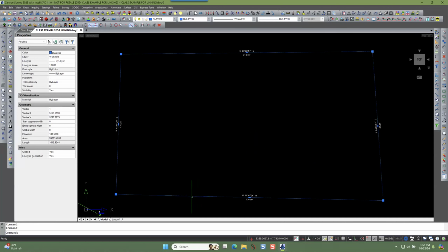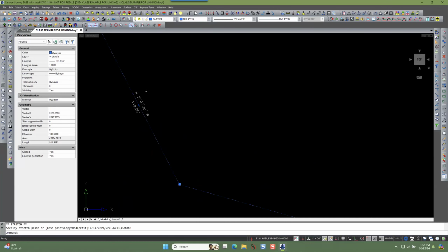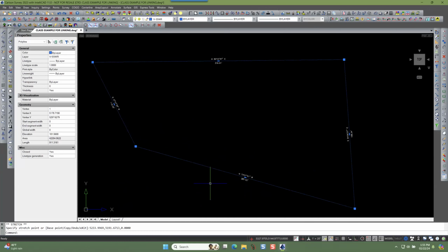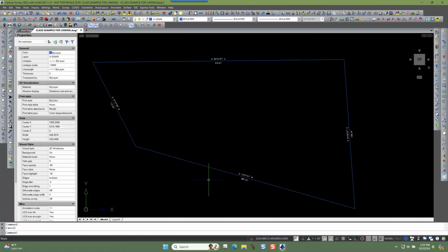Now, this was the other linking, linking labels with line work. So if I select that and say move this up, notice, keep an eye on those values. I had 176, and it was a north 02. It was almost due north at 176 and almost due east or west at 336. So if I click up here now, notice it recomputes and redisplays the annotation automatically because I had it linked.